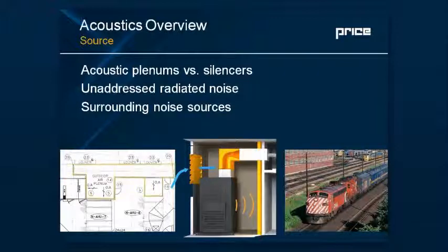And what that does in the bottom left there is it not only allows for a lot of noise absorption, it also allows for easy access for maintenance or cleaning. And it also comes as a rated assembly. So instead of dealing with the architect and having the sheetrock guys come in and not knowing how that assembly is ultimately going to pan out, especially if there's moisture concern, you can use an acoustical panel assembly to address that noise source.